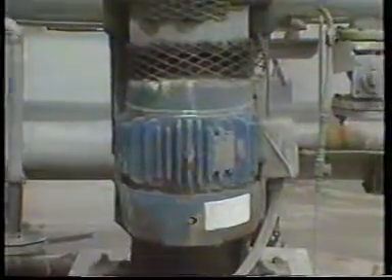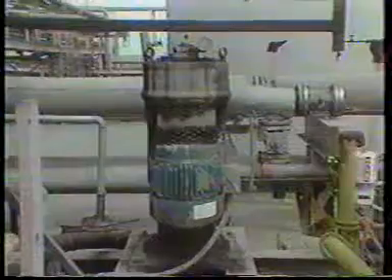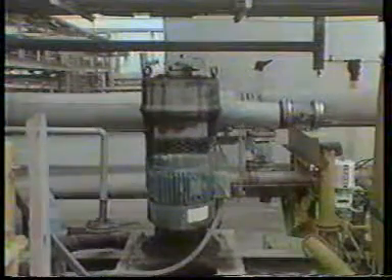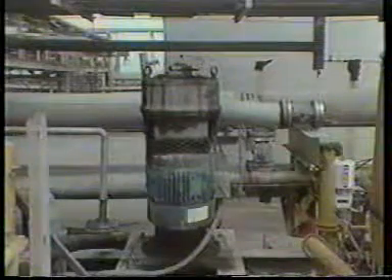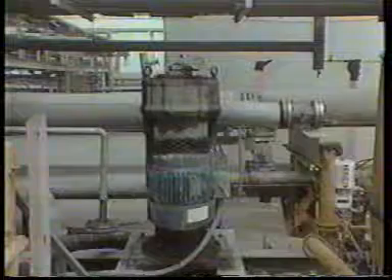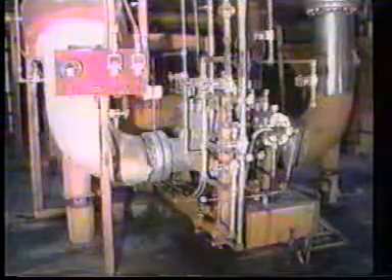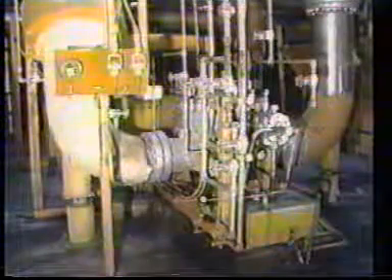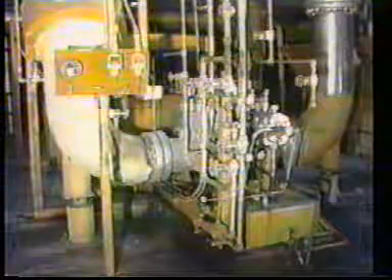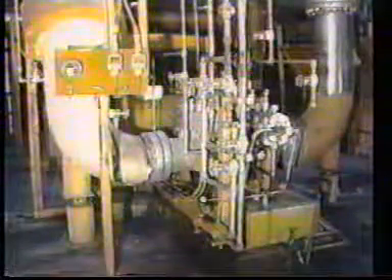Let's talk about these extraneous voltages, which are often referred to as noise. Noise can have a serious effect on measurement accuracy. This is because the voltages induced into the flowing liquid and picked up by the electrodes are so small. The addition of noise will therefore produce an error in measurement. Noise can be corrected by using a reference current from the same source. The circuitry of the voltage measuring device can isolate irregularities in the reference current and filter them from the meter output.